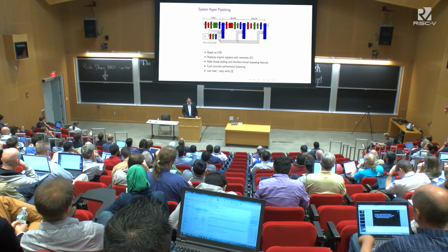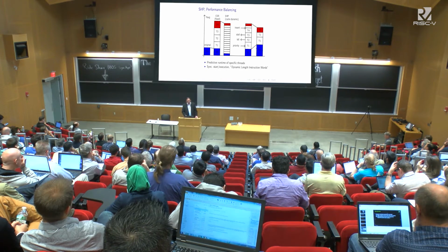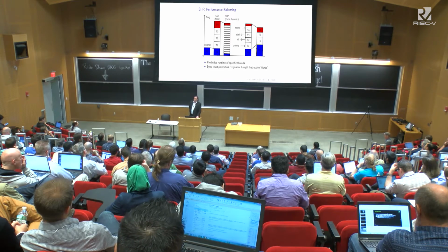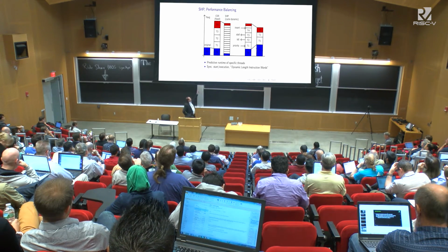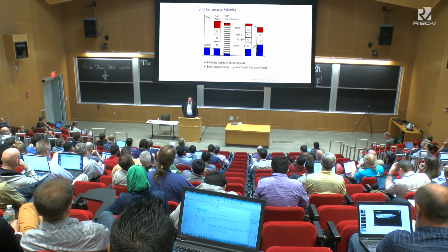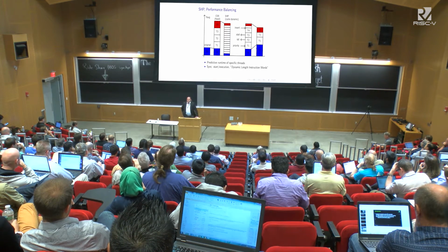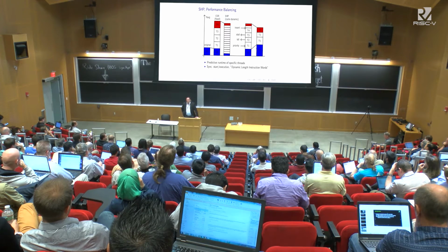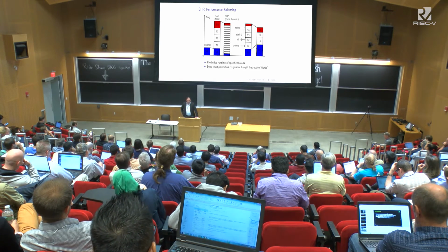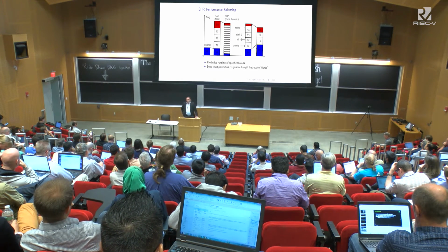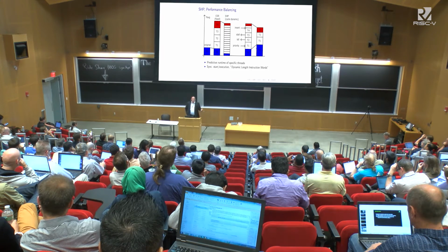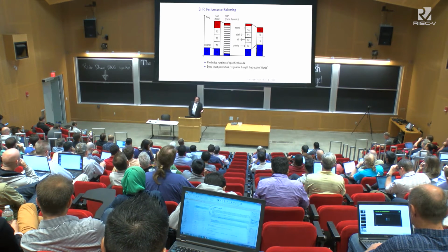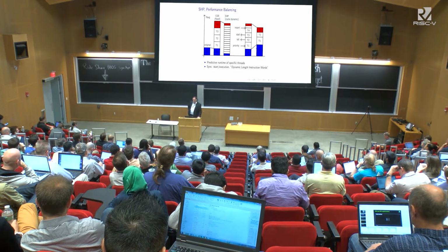Okay, so let's compare the different scenarios. We have the original design here on the left. And when you apply Slow Retiming, you have a fixed thread order. You cannot change that. The first aspect is that with system hyperpipelining, you can run more threads if you want, but you can easily switch between the minimum threads and the maximum number of threads.